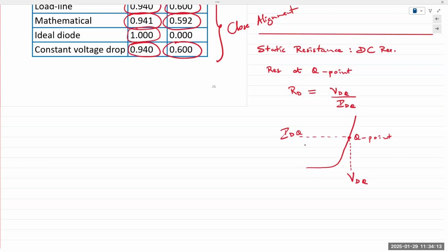Yes. So RD is the internal resistance of the diode. Again, overall, the diode is non-linear, but there are some portions that are linear. So we can apply some linear equations to some quantities. And if you recall the PSpice simulation for the diode in the lab, one of the quantities we specify is RS. RS is the series resistance.